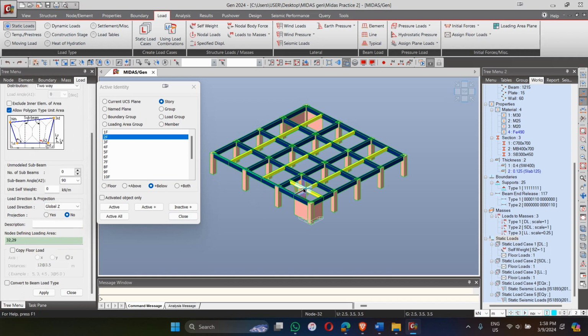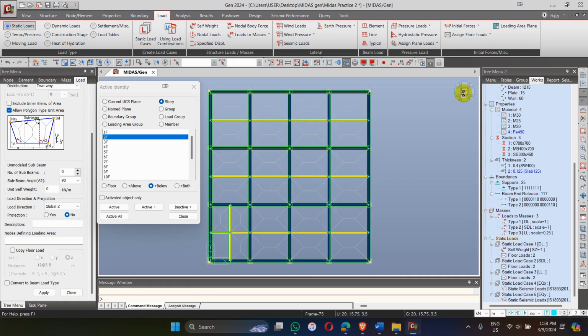Okay, here this is the shear wall void, here, here, and here. So we see the floor load has been applied on the beams with the tributary area. This portion of the load is applied to this beam, and this triangular portion to this beam, and so on to all of the beams.